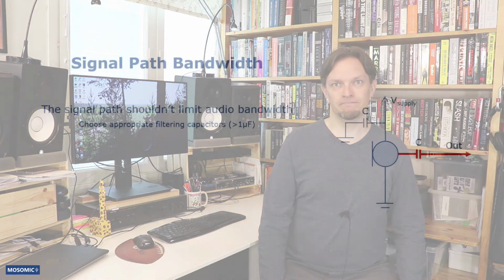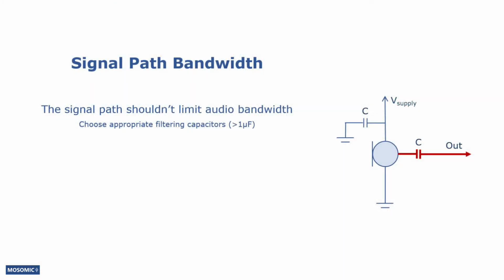It's also important to make sure that the maximum signal frequency that the signal path can handle is high enough so that it doesn't limit the capabilities of the microphone system. There are typically direct current (DC) filtering capacitors in the output lines of analog microphones to remove the DC component from the signal. These capacitor values must be chosen so that they don't limit the bandwidth the signal line can transmit. 1 microfarad or higher capacitor values are commonly used. There may also be other filters or components in the signal path that may affect signal bandwidth. In ultrasonic systems, it should be noted that the bandwidth requirement may be tens of kilohertz.